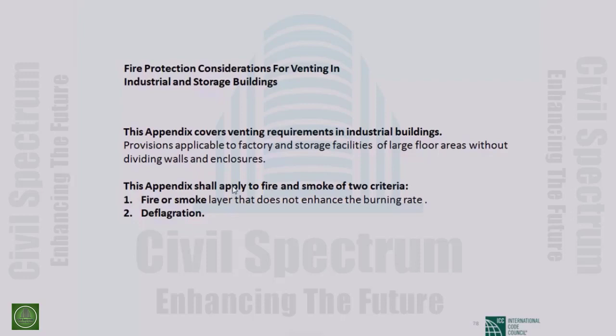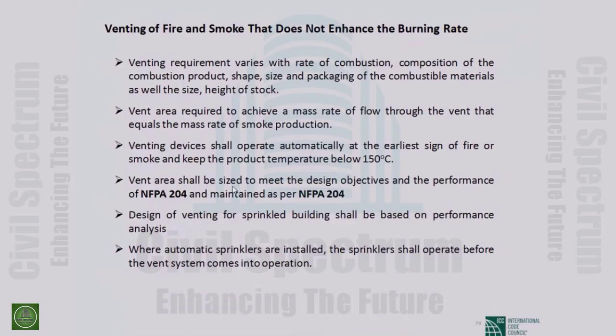Actually, between detonation and deflagration there is a narrow band of difference. Deflagration starts from a normal fire and goes to a very high velocity. We are talking about the venting of fire and smoke that does not enhance the burning rate. So for this type of burning, you need to provide smoke-releasing vents.